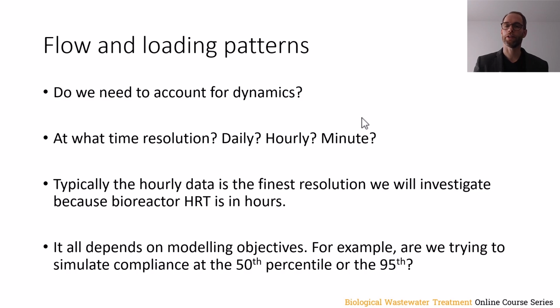And so variability in the influent on a minute-to-minute basis will typically be buffered out in the bioreactor based on its HRT. But then should we be looking at the variability on a day-to-day basis, or an hour-to-hour basis? How important is it to capture those extra breakthrough peaks in the effluent that we saw on the hourly basis compared to on the daily basis? Well, this all depends on our modeling objectives. We need to ask ourselves questions.